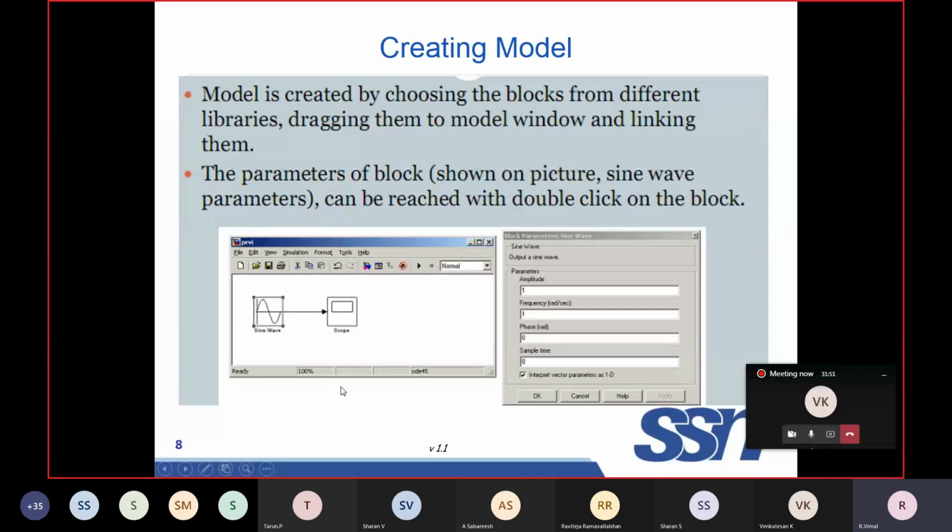So to create a simple model, here I am taking the scope. Scope is nothing but a sink, and sine wave is nothing but an input. I am connecting an input with an output. So this is how we create a Simulink model. To create the Simulink model, I'll just drag them and pull them into the workspace, and I can set the parameters.